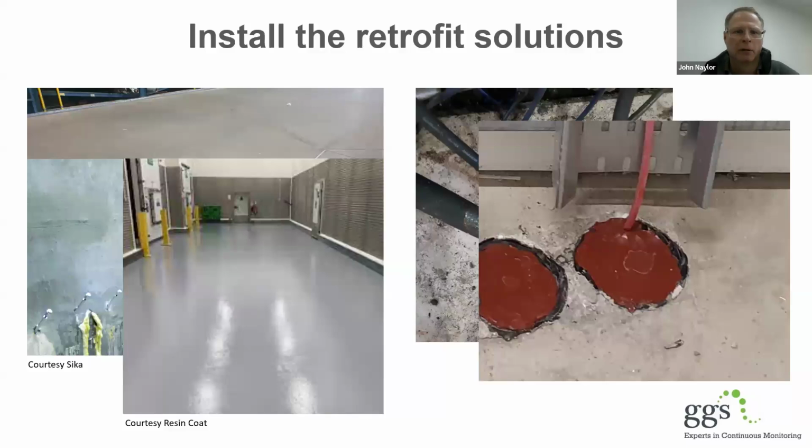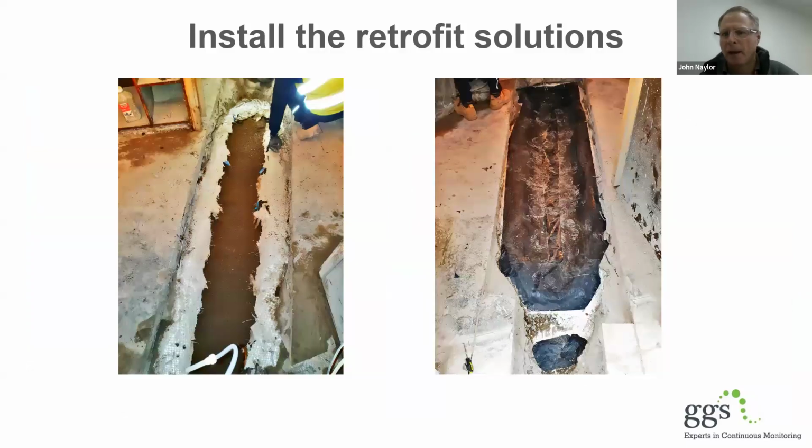And what about the simple repair here? Here we've got some trenching going in for some new services. The services are already in. It's now been sanded up, bedded. The membrane that's already there has been exposed. Maybe not the neatest of jobs, but they've actually done quite a good job there on the left. And then on the right-hand side is the retrofit membrane that's gone in before they reinstate the concrete slab. You might notice that that shape there is like a body shape.